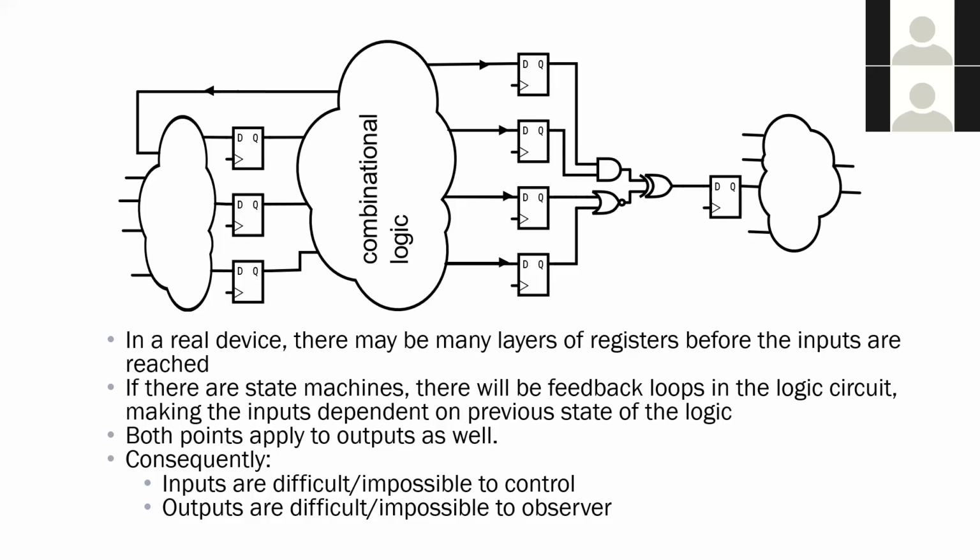Now, the idea is that every node in your ASIC needs to be tested. What do I mean by node? Meaning, let's say if I take this 2-input AND gate, it's driving this XOR gate. So there's a node. We call the connection between the AND gate and the XOR gate a node. So we need to find a defect there. The node includes the pins. So every node in this circuit can have a defect, and you need to be able to run tests so that a defect on any node is caught.